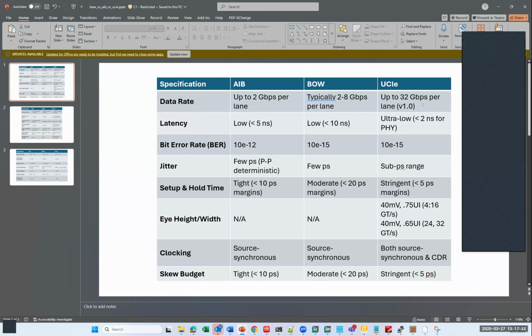Okay, but from a design point of view, we are designing the IP to be spec'd up to frequency X, and all the design that's ongoing is meant to hit that frequency X. Then it will be the actual operation that determines where it can hit frequency X, or if the software is smart enough to fiddle with the registers and get it to X minus 5% so that it's not dropping to half X, right? It's still finding the maximum frequency that it can operate. Yeah, I think that can be put together.